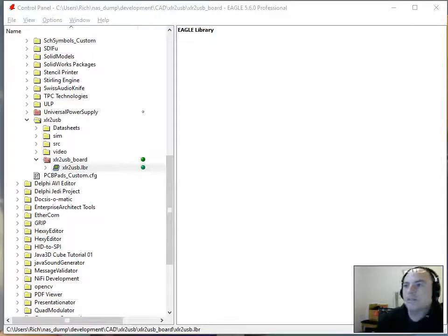Alright, in this episode we're going to create a few new interesting schematic symbols that will be very useful to us. And along the way we're going to show some more Eagleness that's very useful for us. So the three things that we're going to create are a title block, an accessory part, and a voltage supply, which could also be a ground. In fact, we'll create both of them because they're so fast.